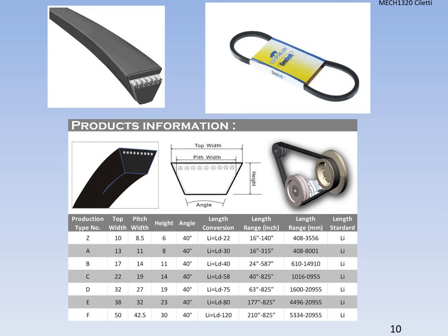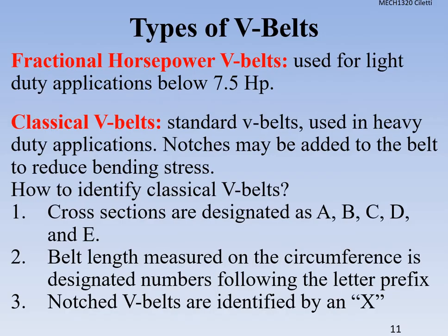And you can kind of see, based on the shape of why it's a V-belt, where it grabs the side of the sheave and uses friction to pull it. So the sheave actually has a groove that matches the V, that matches the size of the belt. So it is important when we're sizing belts and things like that.